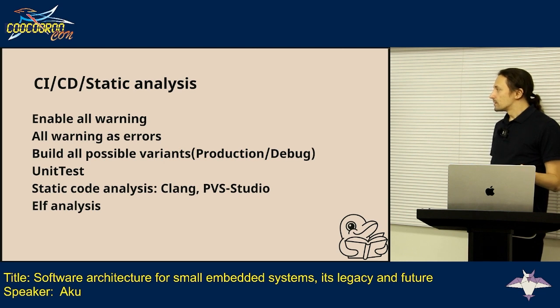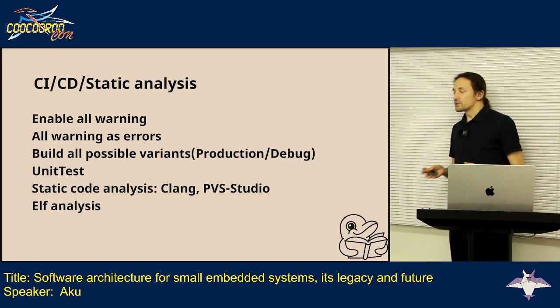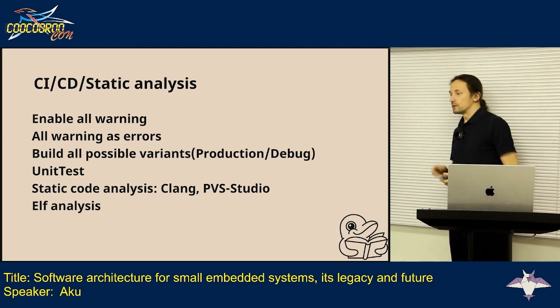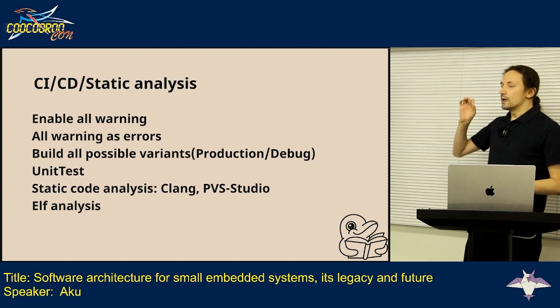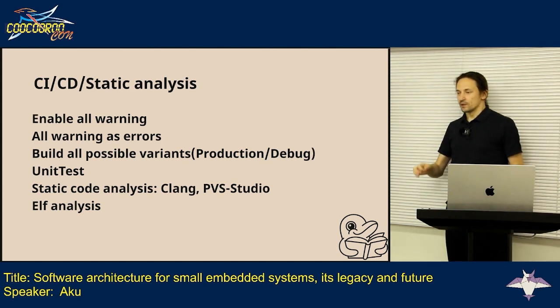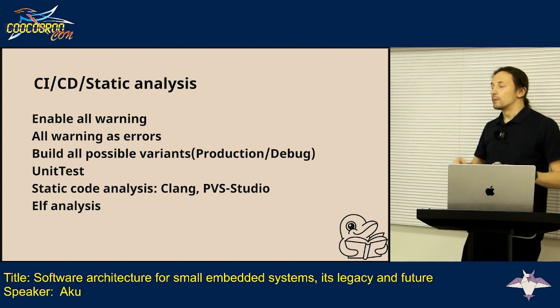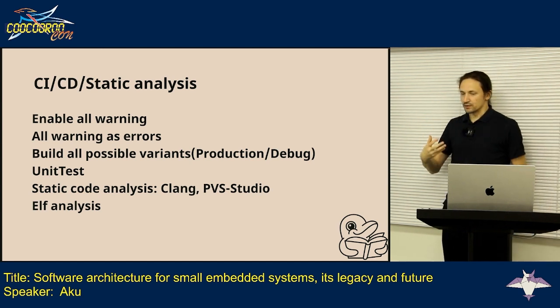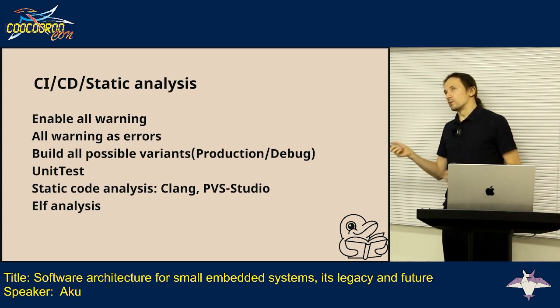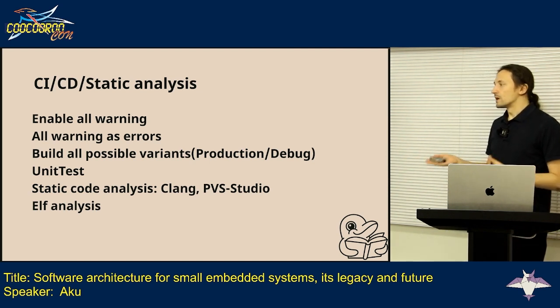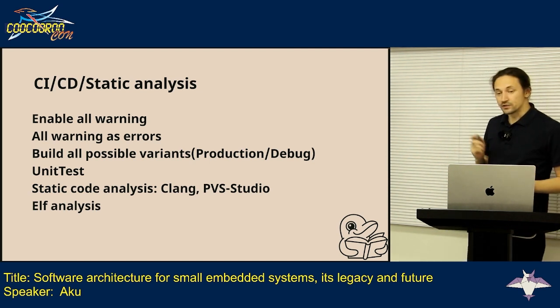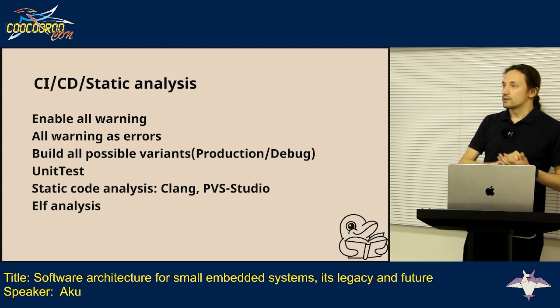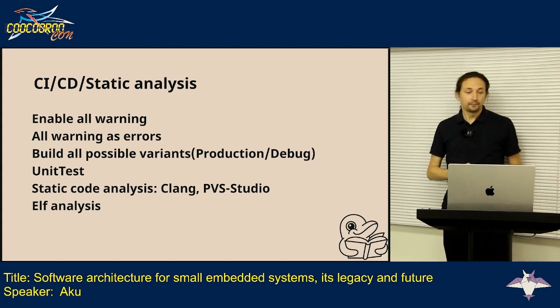Some specialized vendors like IAR or Segger provide them, and some of those tools are actually quite advanced. All those new chips have the ability to trace everything that happens in the chip, like interrupts and how much time you spend in them. But usually these features require quite sophisticated software to control them, and that's where open source tools usually lack support for those additional features. That's what you can get with proprietary software.